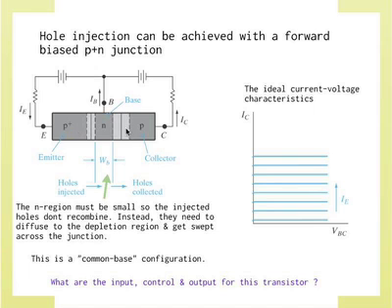Then you have emitter base, which is the hole injection part, which is forward biased. So think about this PN junction first, which is reverse bias. You have a reverse saturation current flowing, which is independent of the reverse bias voltage. And that reverse saturation current can be controlled by hole injection from this forward bias PN junction. That's a qualitative picture, and you need to understand that. Of course, the details are a bit more complicated, and we'll look at those today.